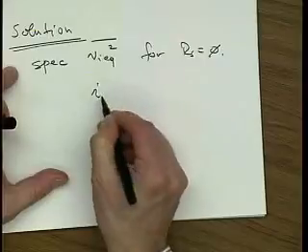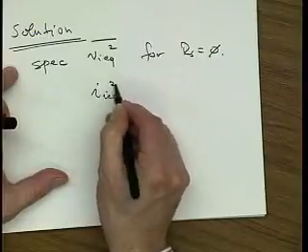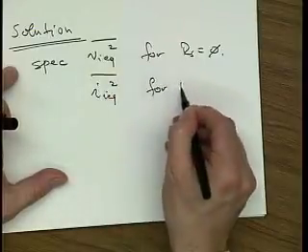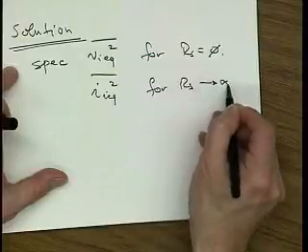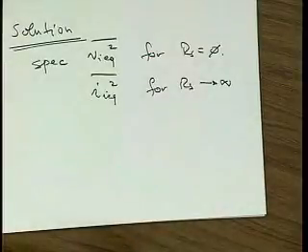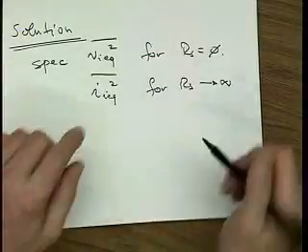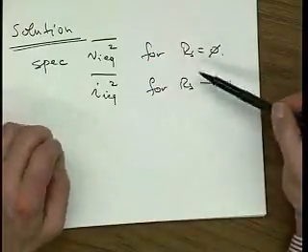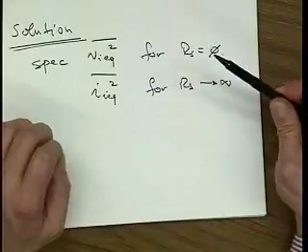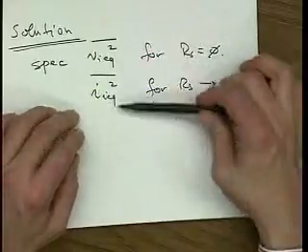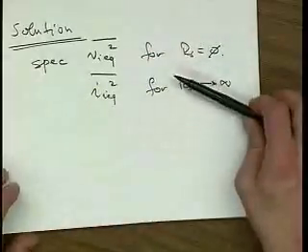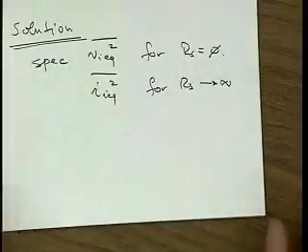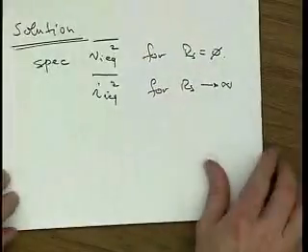And we also specify IIEQ square for RS infinite. Then afterwards, when we have an RS that is somewhere in the middle, we can combine these two results and get the correct noise at the output for a circuit, independent of the value of RS. Okay, I think I need to speed up.